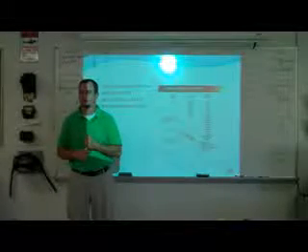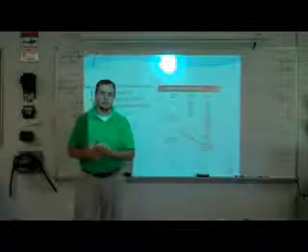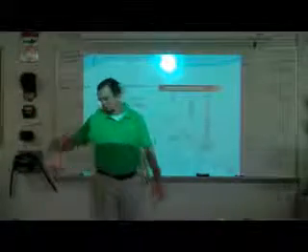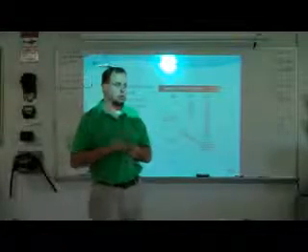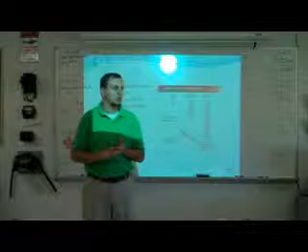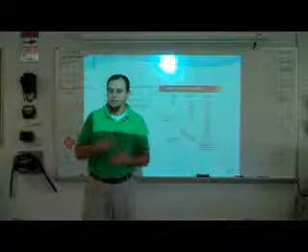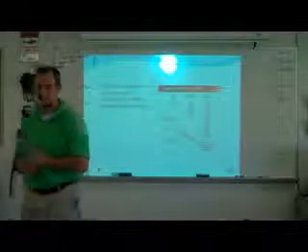UF? Underground feeder. That's for direct burial. I know you don't know that. Does that mean you don't have to put it in conduit? You can just lay it straight in the ground. The moisture in the water and the dirt is not going to affect the insulation. That also is sunlight resistant.